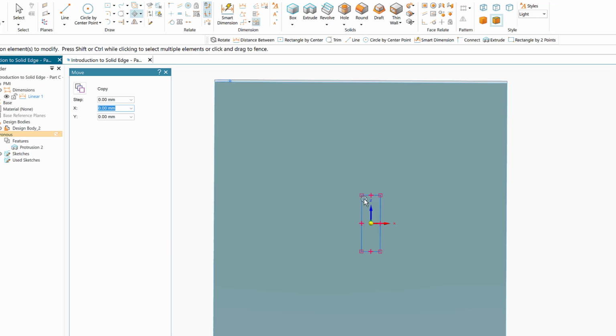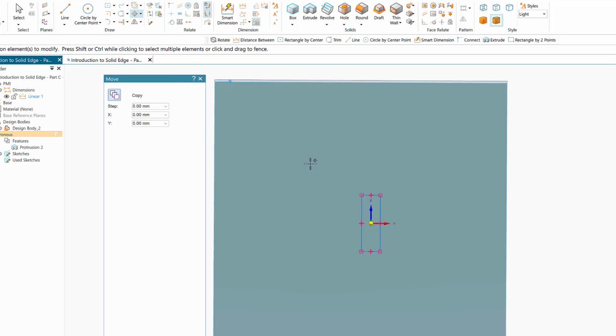If I want to move a copy of it, I'm going to highlight the copy, make the copy on. So I highlighted the copy, this way it becomes on. Now I'm going to highlight this shape here. I can use smaller steps, like say 10 for example, but I need to move it to any location, say 50 by 60.